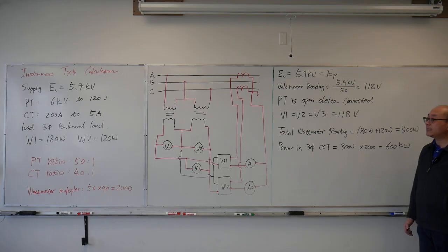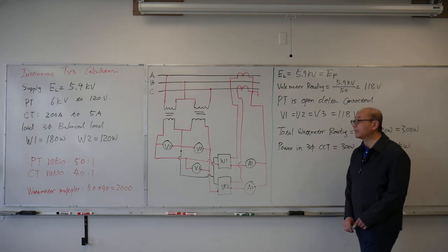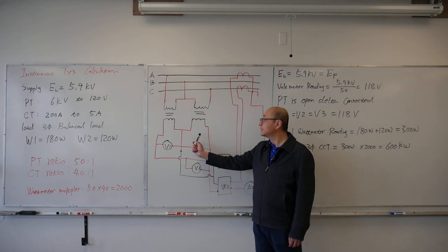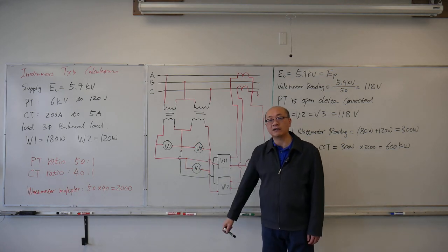So this is a pretty easy circuit. The only thing people tend to get confused about is forgetting that these 2 PTs are open delta connected.